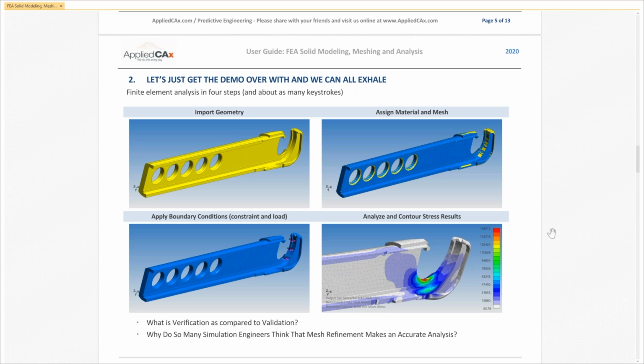We use this in class because this part here has a yield stress of 100,000. So anything over 100,000, it's like, well, that's not going to work. And why it was so high is because we were given loads that someone pulled out of, well, we won't say where they pulled them from, but they said, oh, use 40 pounds because we want to be conservative. So get this. They were applying this 40-pound load on this little surgical anvil as part of their QA. And if it passed, they would sterilize it and ship it off to the doctor. And then the part would fail, not always, but occasionally inside the patient, and they couldn't figure it out. And they were shipping pre-cracked parts.